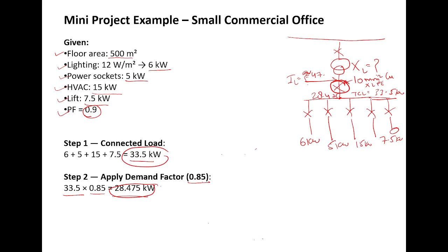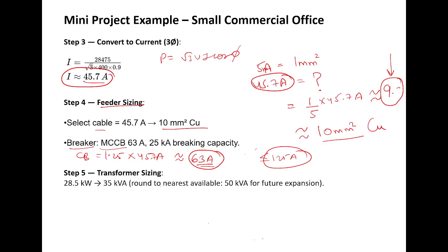You can make settings in MCCB, so you can easily use your additional load, but there is no such provision in MCB. That's why we are using MCCB. Okay, I have got it. Sir, in MCCB there is the provision for adjustment. Yes, exactly.